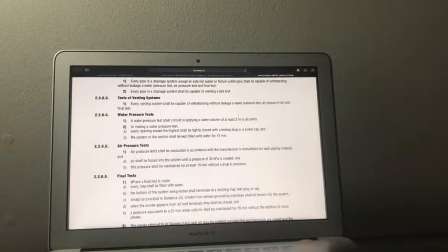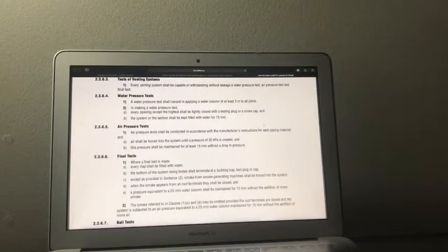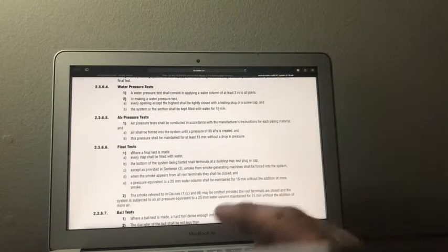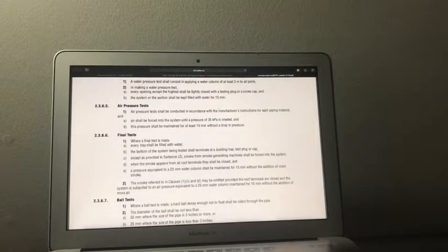And to touch on the subject as well, when we cut it down to 5 feet, that's a bylaw that I have read from the Vancouver bylaw website, at least for plumbing bylaws. So that's where that 5 feet comes from, just to put everything into perspective here. They're saying one thing, but we practice another. So that's where that comes from, the Vancouver bylaw, that we can cut it down to 5 feet as well. It says it shall be held for 15 minutes. Everybody knows we just leave it until the inspector witnesses the water test.